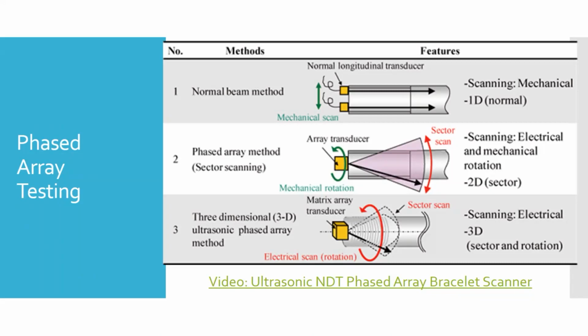So that's one. The other one shown here can actually be done for 3D scanning. This is what's called a matrix array. Here you've got multiple transducers, a matrix array, that are all doing that sweep function, like what's shown in the middle. Put that all together, and because you've got multiple sensors looking at the same spot from the side, you can start to actually get that three-dimensional mapping of it, rather than just a single one that looks at height differences.